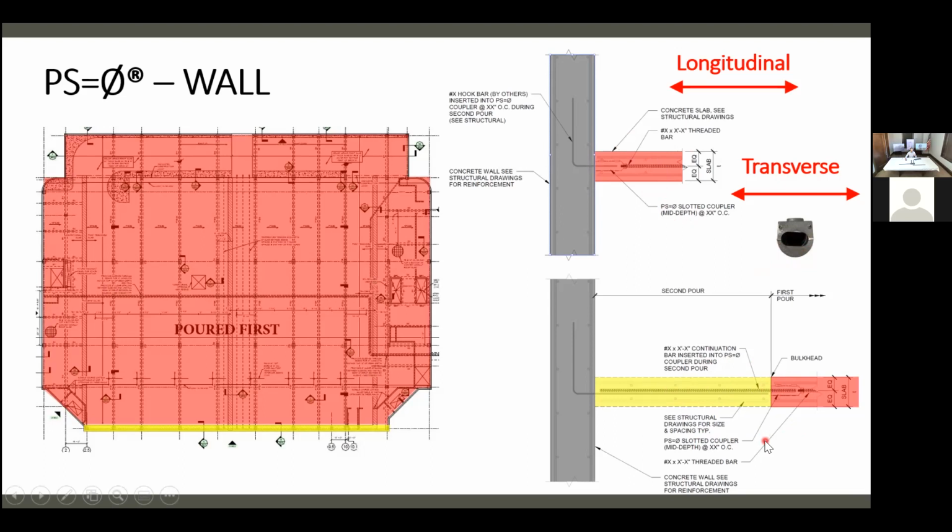We're using these at shear walls, leave out places where normally the engineer doesn't want to lock the wall in right away, which causes a lot of issues later because they've got to pour back these little strips. I mean, it's just fantastic. And they're just coming back later to grout our couplers.